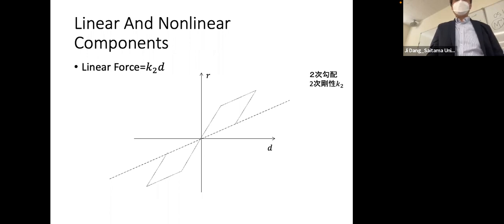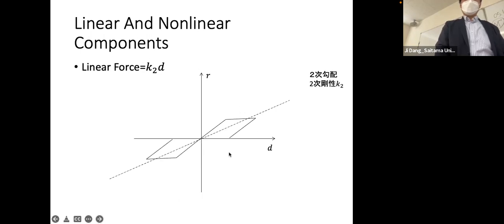So any unloading elastic line across this line will be split in half. One half will be the positive side, the other half the negative side. Using this gradient, by removing the second stiffness, the hysteresis force will return to this second gradient. So I'll put them down here. You can see that the second stiffness will become 0, and this stiffness will become K1 minus K2.